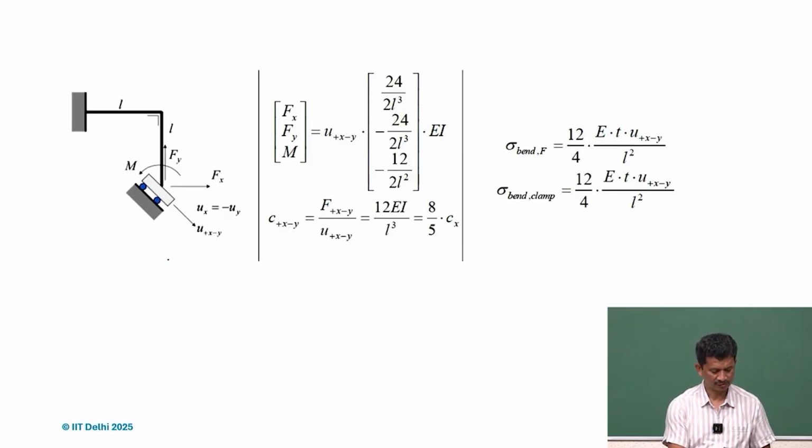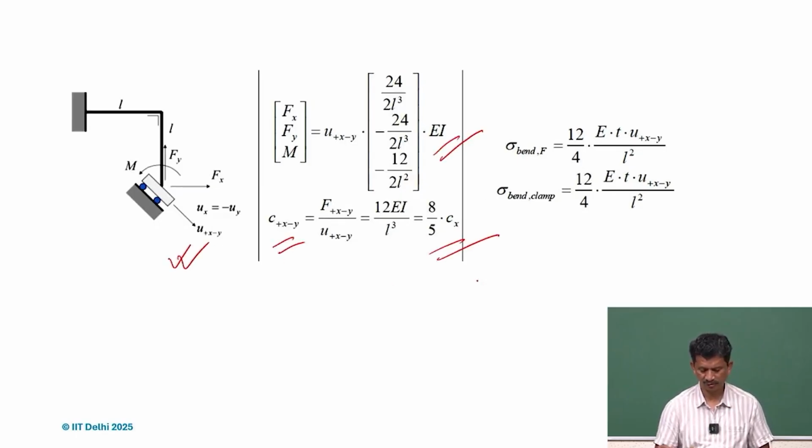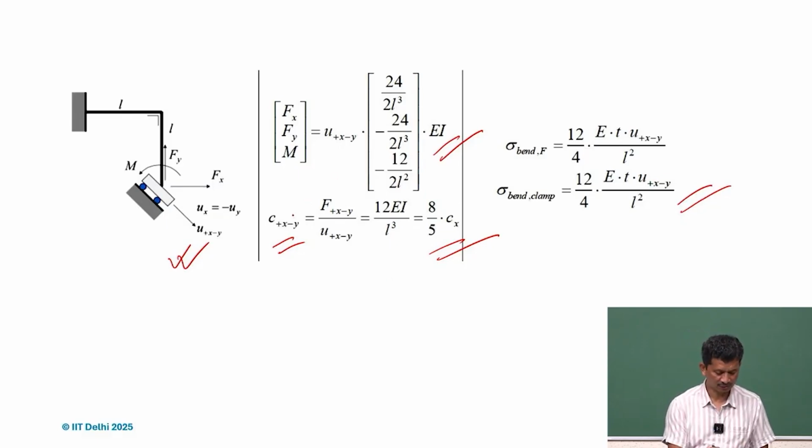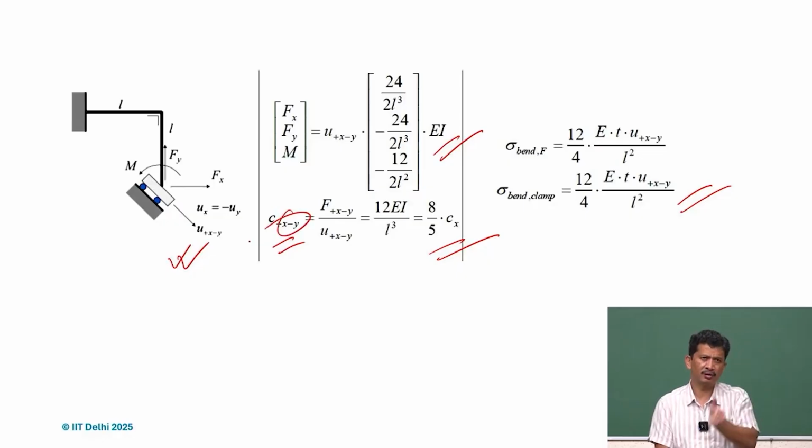Likewise, we can get this kind of formulation. It's again only one DOF. We are giving actuation, and this is a kind of constraining equation. It's only moving along the slope. So here we may have Ux and Uy, but they are not independent. Only one parameter can be independent, the other follows it.